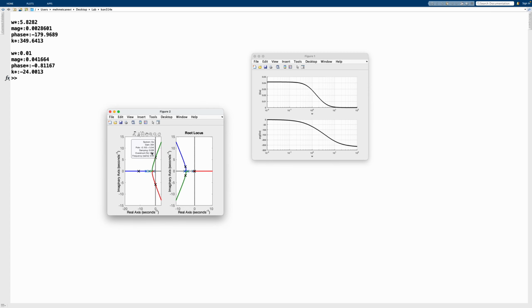also some other similarity here where you can see that the frequency, or the point where omega on the j omega axis is, is basically the same value here. So even if we plug something into the characteristic polynomial, and if we're using the Bode method, they're not quite the same, but of course the frequency or the crossing where it happens is going to be the same. We have numerical differences, but theoretically they're equal to each other. So if you see a certain frequency here, you can assume that the crossing is also at that point.